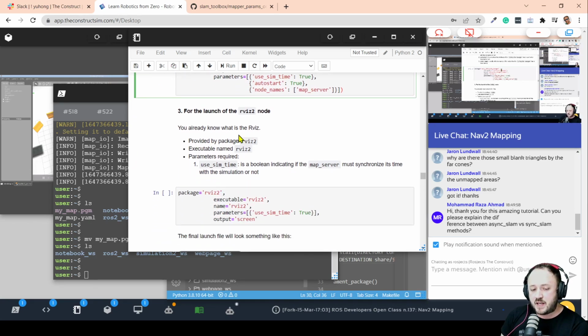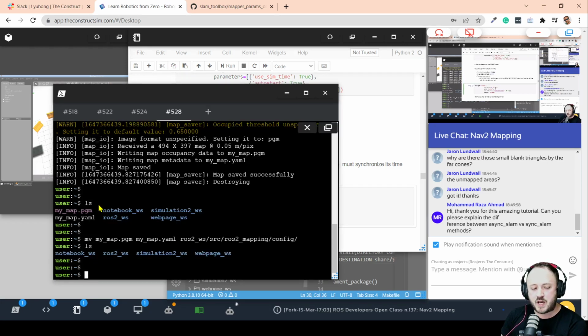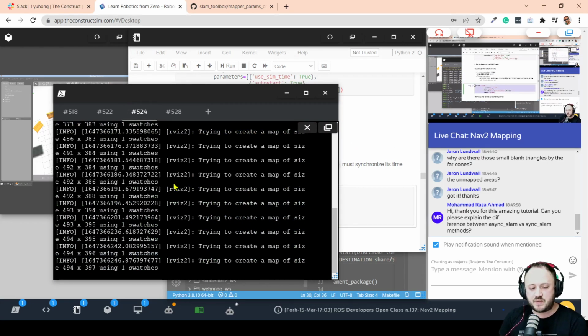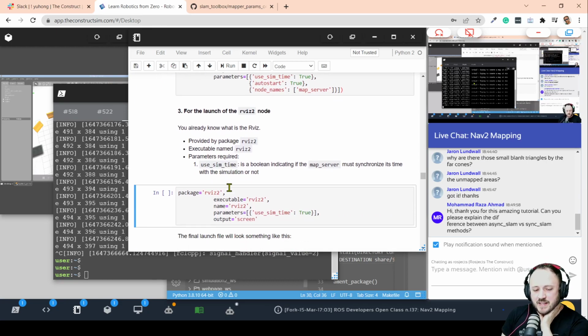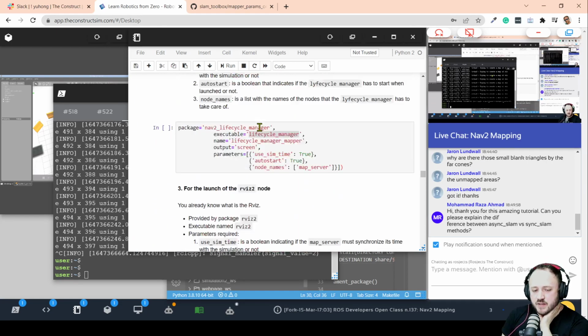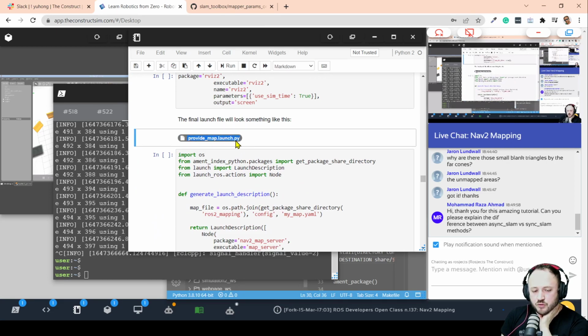And then finally, I'm going to also automatically start here an ROS2. Okay, this is not mandatory. We are going to just add it here to the launch file so that we don't have to be starting ROS all the time here. Okay, then let me stop here ROS, and then let's combine all this into a launch file, which we are going to name like this: provide map.launch.py.